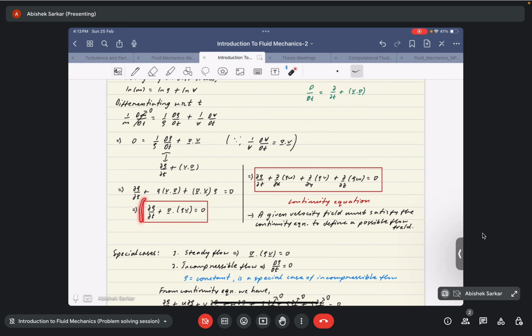This equation corresponds to mass conservation, which has an additional term: the divergence of the velocity field multiplied with the density of the flow. It is just important that you don't confuse this equation with this differential operator. I just wanted to make it clear that if we now expand this equation, and this is a vector equation, which is valid for all coordinate systems.